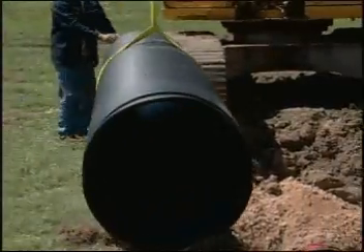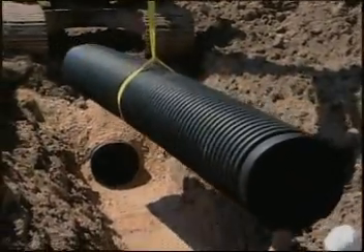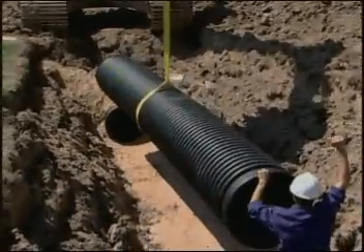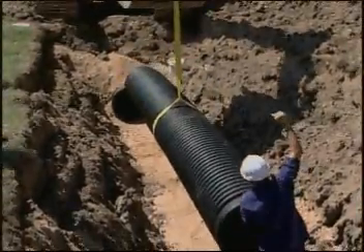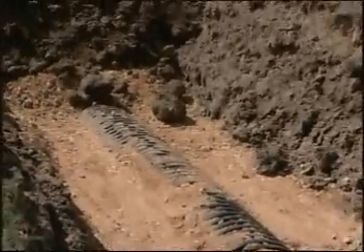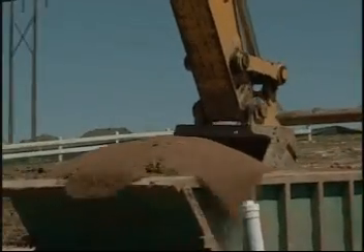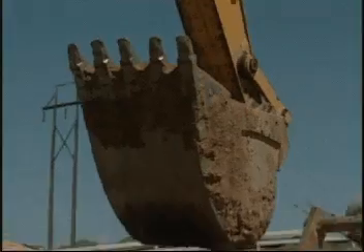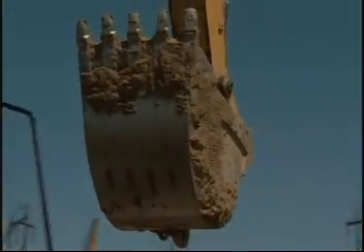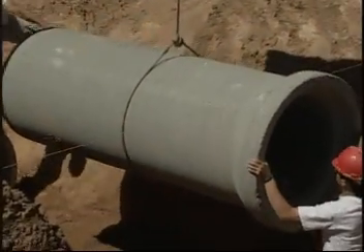Corrugated HDPE pipe, as well as various other flexible pipe products, offer only one strength choice for a given diameter. Invariably, the primary structural strength must be provided by the embedment materials, which oftentimes must be imported to the job site. While the quality of the embedment materials selected for concrete pipe will impact the soil structure in the pipe soil system, the pipe will contribute up to 95% of the system's structural strength. So, haunching material is rarely critical for concrete pipe.